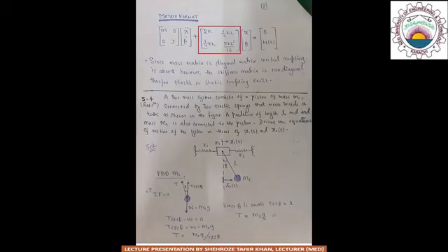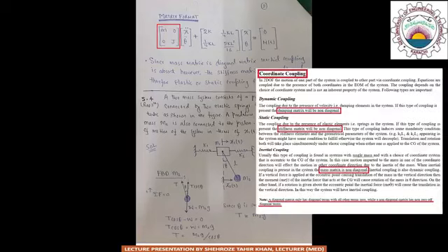It can be seen from this form that the mass matrix is diagonal in nature, because the diagonal terms contain the mass and the polar moment of inertia, while the other terms are zero. As we studied in the previous lecture, in order to have inertial coupling, the mass matrix must be non-diagonal.